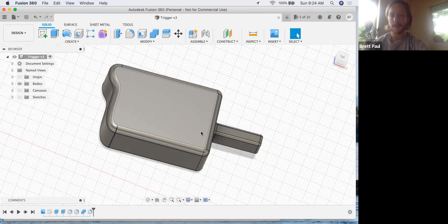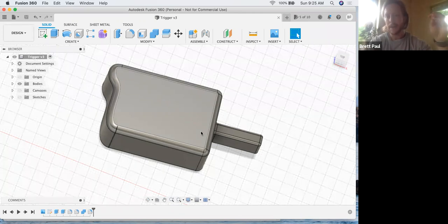And we're also going to apply a material ID. That's used for determining, say, you have a specific volume here of this trigger. If you apply a material ID, then you can actually measure the overall weight, for example. By clicking on the object, it'll take the volume and multiply it by the specific material's density to get weight. That's just one example of what you can do by identifying or selecting a material for a part.